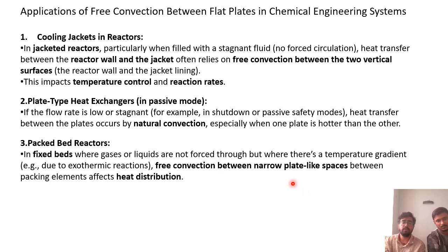And the free convection between these narrow plate-like spaces affects the heat distribution of the packed particles, that is the catalyst. So in this case, we have to make sure that proper heat transfer is taking place so that the catalyst does not get overheated and destroyed. So we have to make sure of that while designing packed bed reactors.